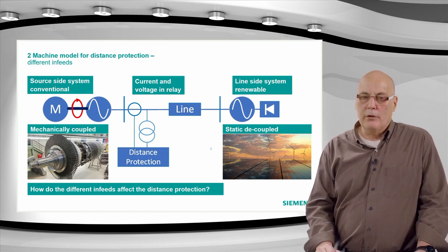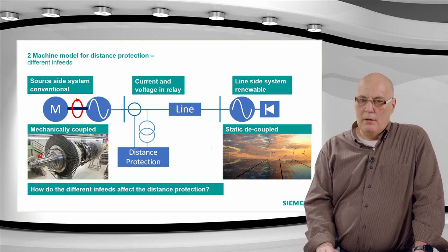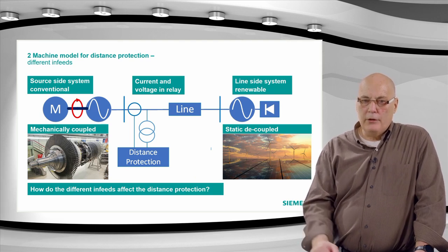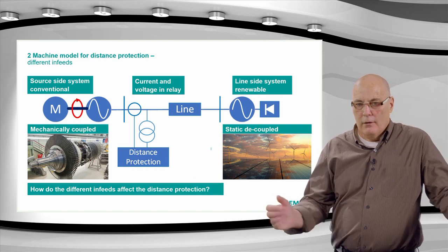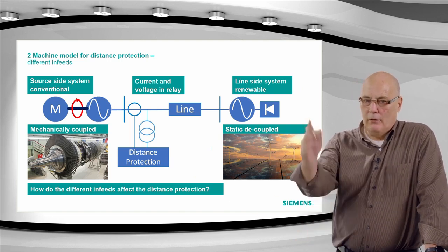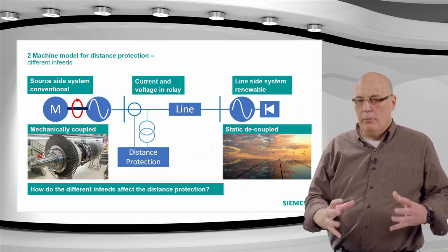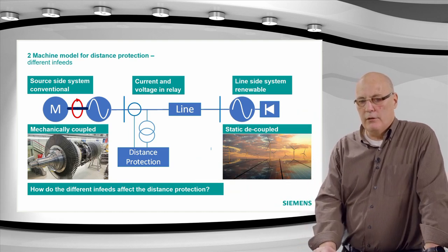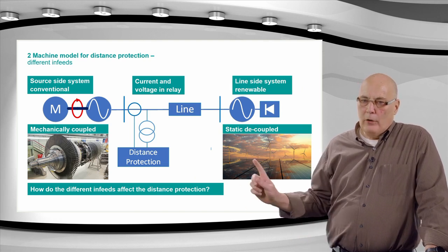It's like a train. You can imagine if you take a bicycle, you can hit the brakes, you can stop in maybe a few meters if you're not going too quickly. But a train or a big tanker cannot stop immediately. It needs a long time. This is what this is. You cannot immediately stop or make the rotational speed of the generator change. The inertia is there.